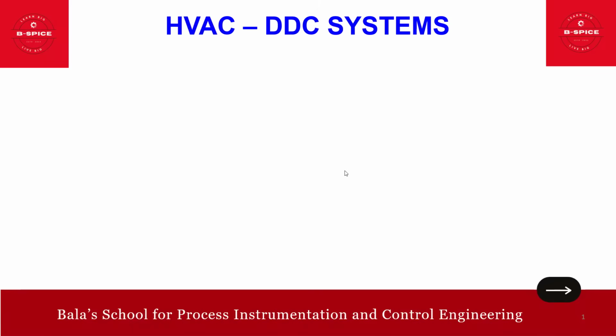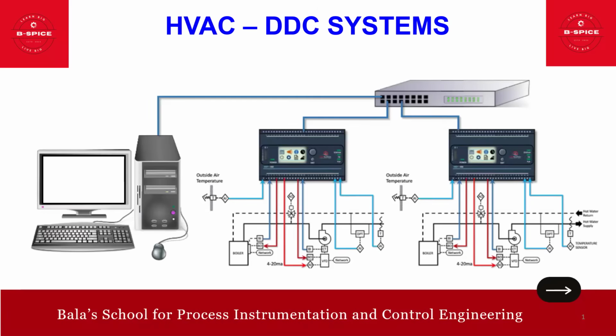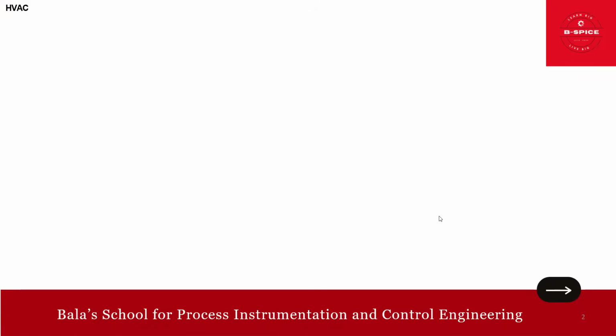In this session, we'll focus on the HVAC DDC system. So DDC means Direct Digital Control System. This is the look and feel of the architecture. You can have this controller, the standby controller, and all your fields are connected to this directly. That is the simple architecture, not like our DCS architecture, wherein we have the various hierarchy, right? So yeah, let's go into the details.